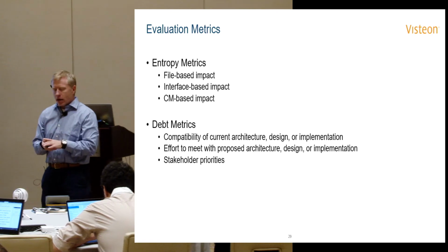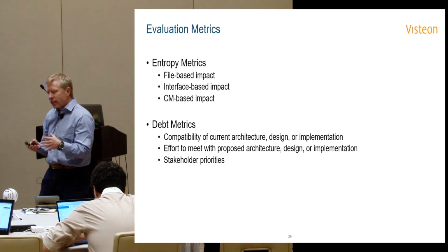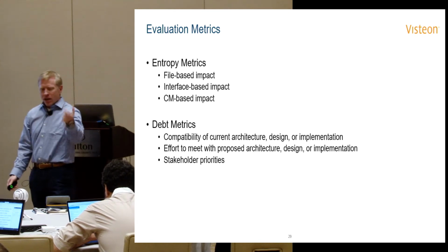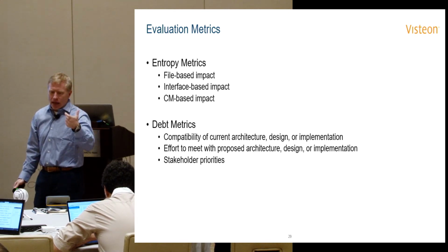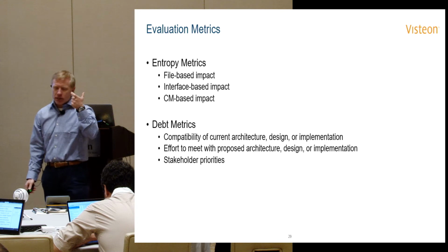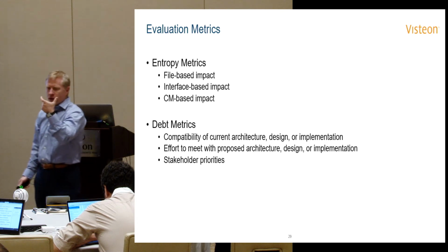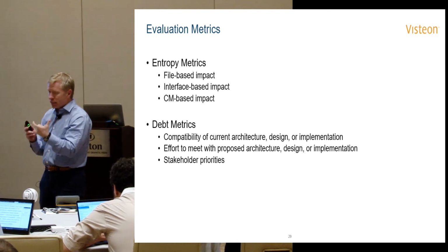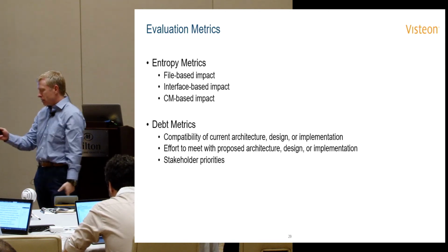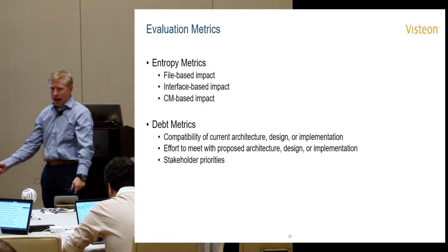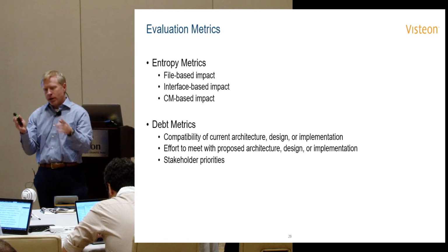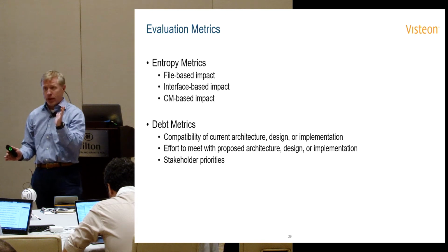One of the big pieces of functional safety is traceability, bidirectional traceability, which means you must be able to trace a requirement from the customer through the system architecture, system requirements, software architecture, software requirements, implementation, test procedures, test results, and deployment and backup, both ways. And someone can come in at any time, pick a random requirement, and require you to do that.